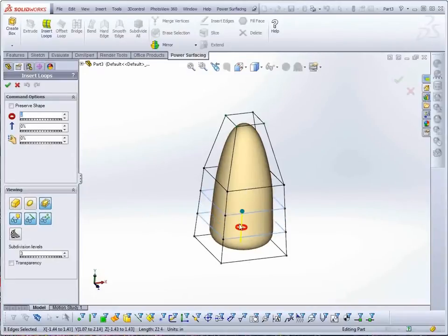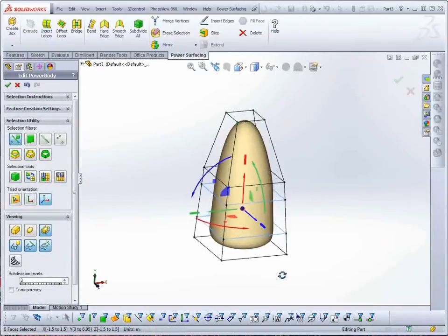Try adjusting their position with the directional gizmo to slide them, or use Pinch, using the round end of the directional gizmo, to move them closer or further apart from each other. You can also affect the parameters directly in the Command Options. Once again, press Escape, OK, or right-click to finish the command.